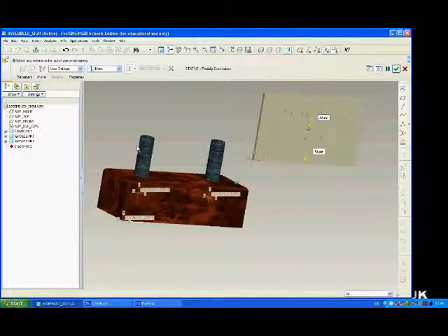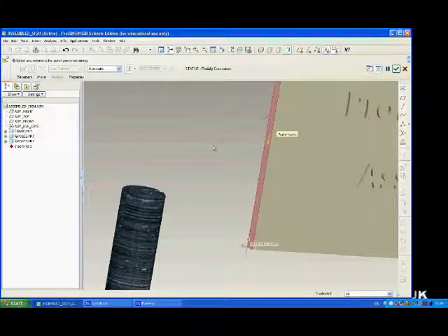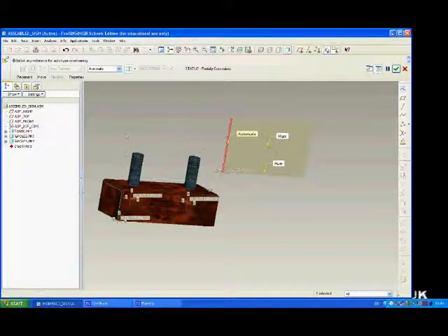Now what we need to do is put this sign here into the centre of this assembly here. So to do that, we're going to select the left hand edge here. And because it's going to match up exactly one of these, what we're going to do is click on this icon here, the little arrow at the side of it. And this allows you to see the different types we have. We've got the connect here, we've got a low distance, and the set distance. We're going to select the set distance here. Now we want it to be a set distance from this side of the base, so we're going to select this side of the base. And you can see here in yellow that we've got a distance shown.